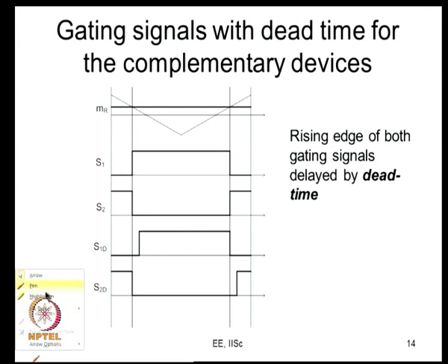What shall I write it down here? So, I can call this time as TD, this is the amount of time. So, it is delayed. Is that only for here, and how about here? Here S1 is first turning off, the top device is turning off and the bottom is supposed to turn on. So, we turn off on schedule, but the turn on we will delay it a little further. So, once again this is your TD.